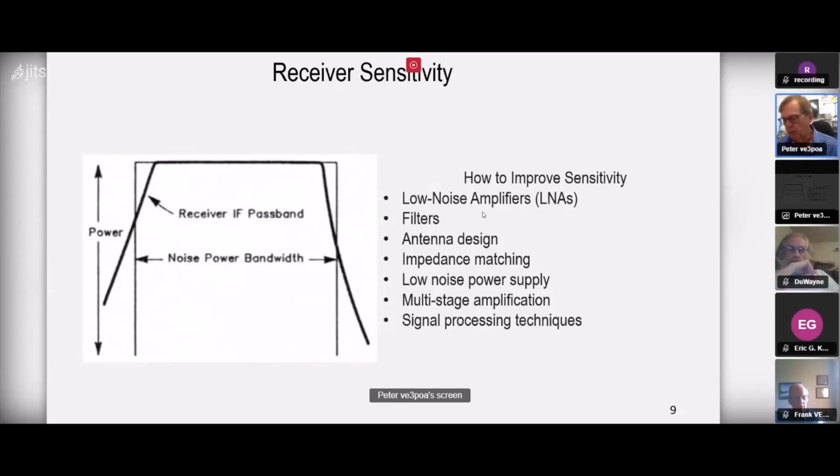Low noise power supply. We've used an awful lot of caps to clean up any of the power line traces, to the point where I was getting tired of installing 0.1 caps. I lost count of how many there are in this particular design. But if they work, right? That's what we need.